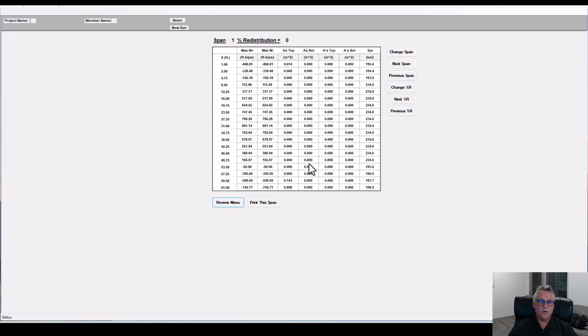So in the factored load rebar review menu, this column is the demand moment. So when we calculated that demand moment, we were at the left side of the interior support, the span 1 side. So we actually calculated 742.7 as the demand moment. This is where we would come to check that. The far right of this is the FPS value.